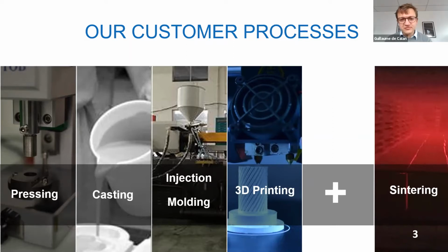I'll go back later on to one, which is quite important for us, which is injection molding. You'll see that this is actually the father of our technology for 3D printing ceramic and metals. All of these processes are indirect processes, what we call powder metallurgy. That means we just shape a body of powder, usually with binders, but then there's always a post-process, which is sintering, and this is very similar to what we're doing in 3D printing.